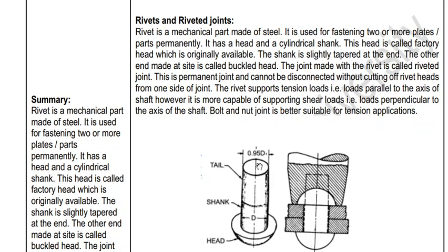So this is not like bolts. With bolts, whenever you want to replace one particular component, you can simply open the bolts and reinsert them again. But in this case these are permanent, so unless you cut the rivet off, you cannot replace any component.